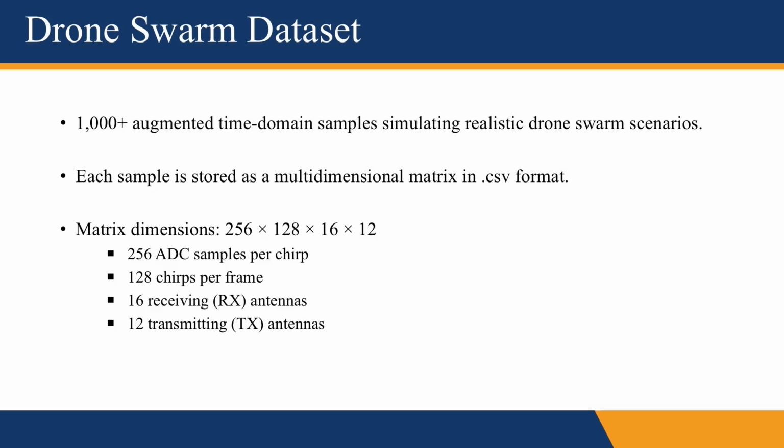We generated over 1,000 augmented time domain samples of drone swarms, each saved as a 256x128x16x12 dimensional data matrix in CSV format, with the 4 dimensions representing ADC samples, chirps, receive antennas, and transmit antennas.